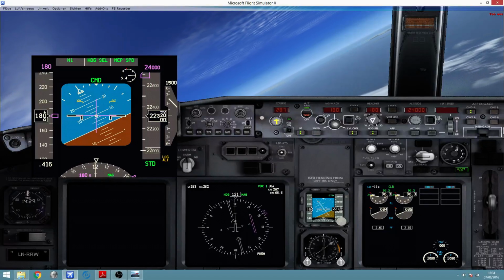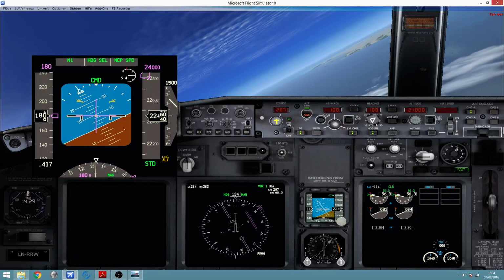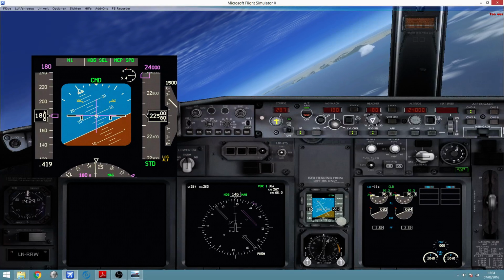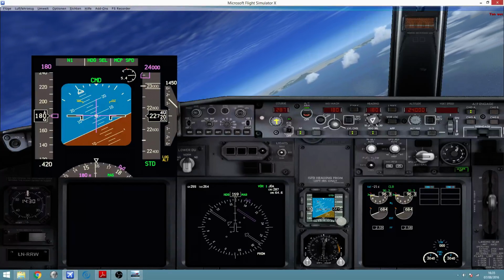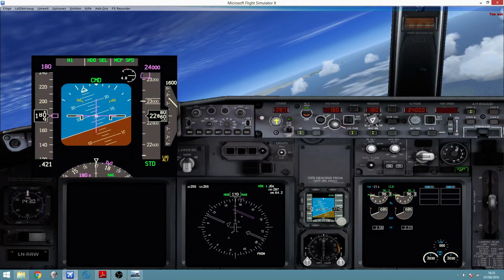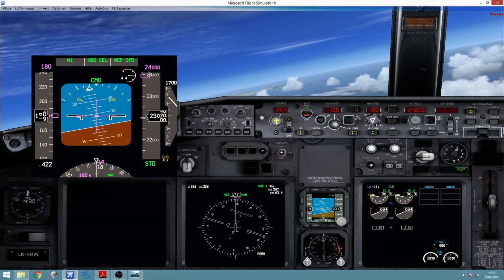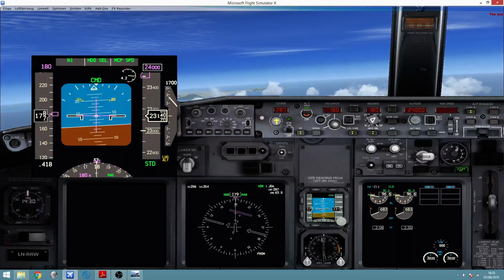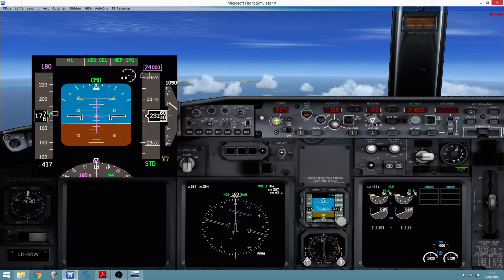All right. So the designer, the engineer that has designed the maneuver is responsible for the separation of the aircraft with terrain if following the maneuver until a certain point. Below that point, the engineer or the maneuver takes no responsibility at all, and it has to be the pilot that, by acquiring visual contact with the runway has to complete the landing. All right, and that altitude at which the pilot has to make a decision and has to decide whether he can continue because he can see the runway or not, is named the minimums.